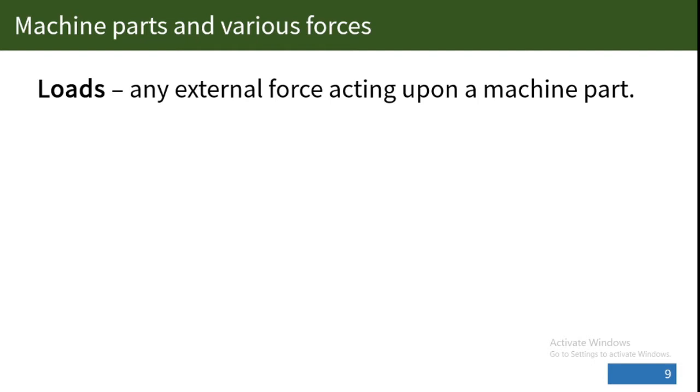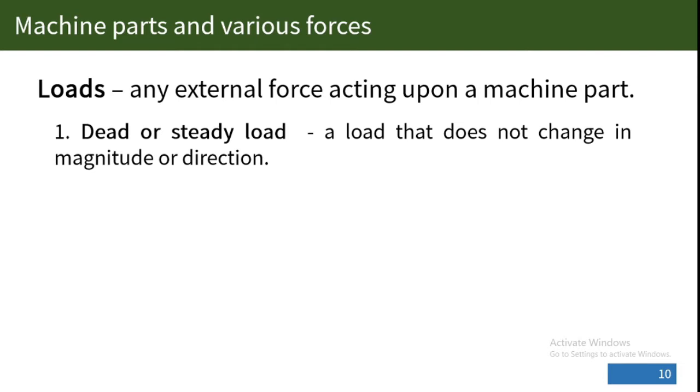Okay. So there are various classifications of loads, and this classification is important in the preceding lessons or modules, because this type of loading will determine how we shall analyze and how we shall design these particular machine parts. First is the steady load. A load is said to be dead or steady if it doesn't change in magnitude or direction.